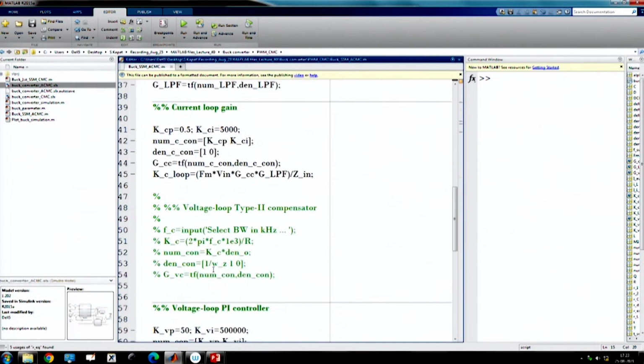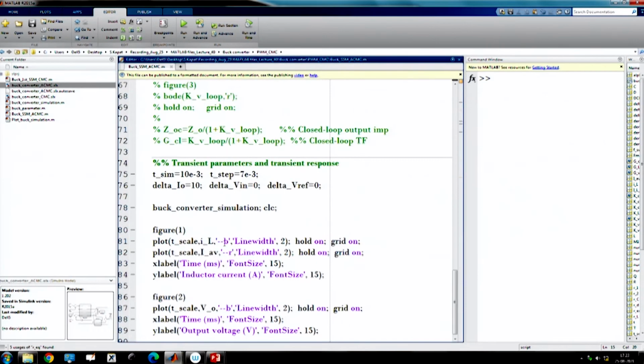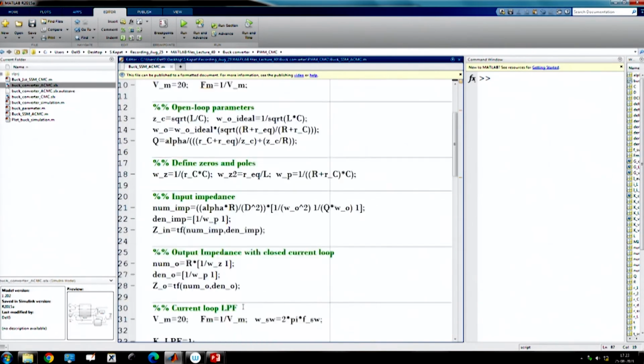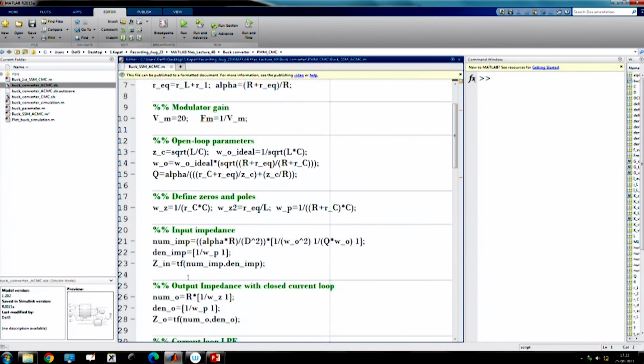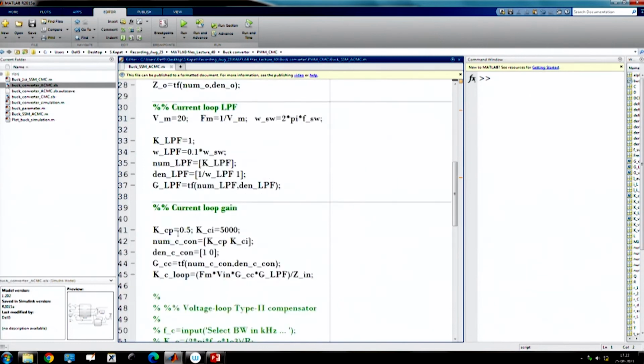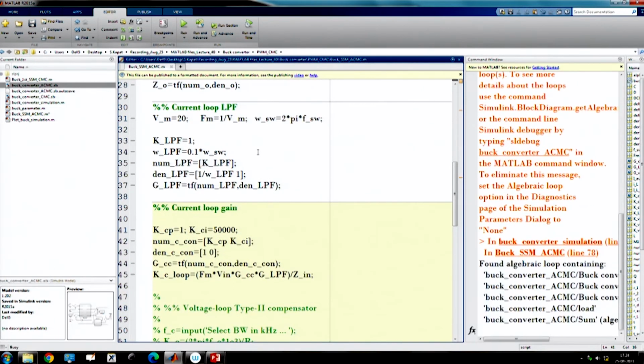This is the effect, using a solid line, and on top of that we want to go to the previous case. So here what we did, we have reduced the integral gain by 10 times and the proportional gain by 2 times. I will explain why it is so and we will maintain the earlier value, and let us hold on and see what happened.